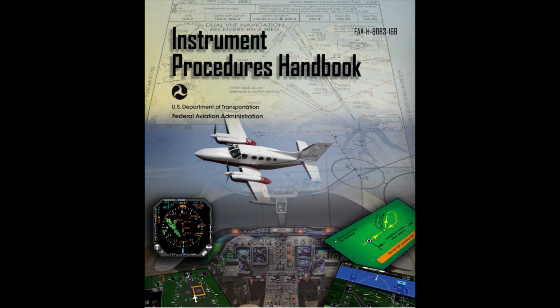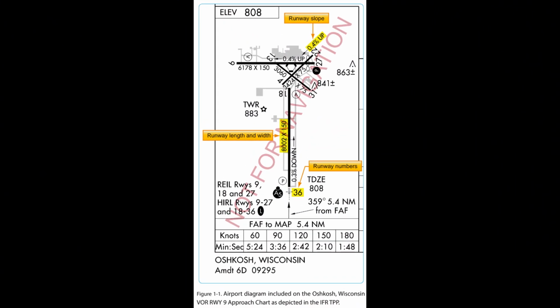Chapter 1. Departure Procedures. Introduction. Thousands of instrument flight rules, IFR, takeoffs and departures occur daily in the National Airspace System, NAS. In order to accommodate this volume of IFR traffic, Air Traffic Control, ATC, must rely on pilots to use charted airport sketches and diagrams, as well as departure procedures, DPs.